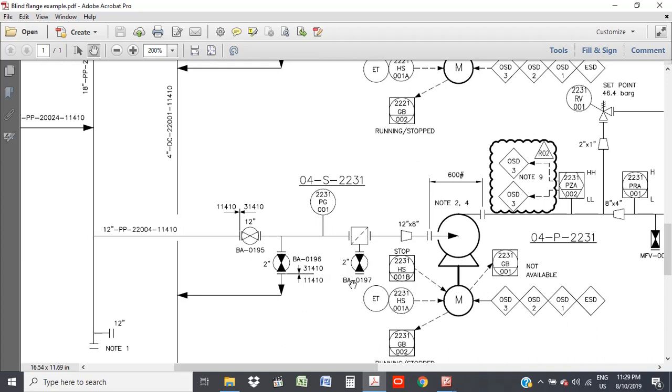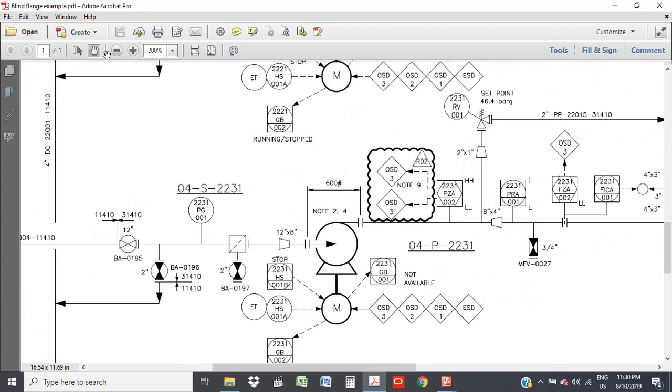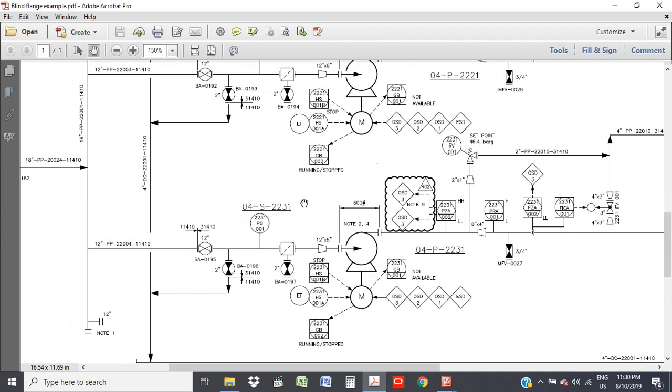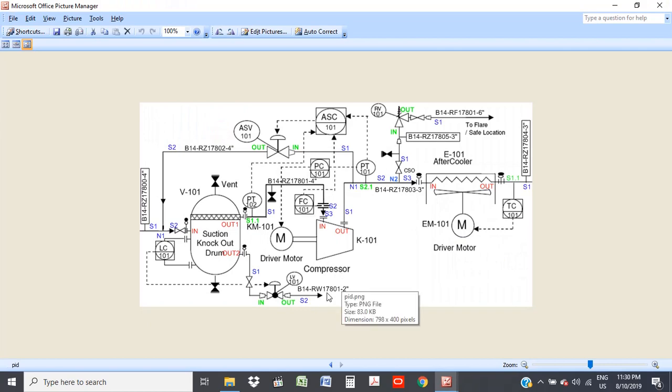So even when you get there and you want to open it, you would see it's blind flanged, and you would know, okay, even if I open this, there's not going to be any flow anywhere. So it's like a protection to stop an error. And in case that happens, that means someone has actually done something deliberately. That means the person has opened the valve and also removed the blind flange, removed all the connections and the pieces.